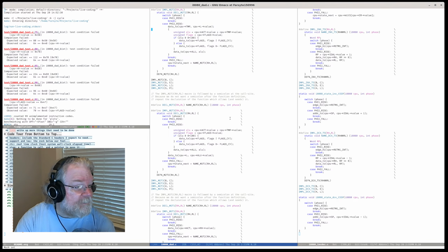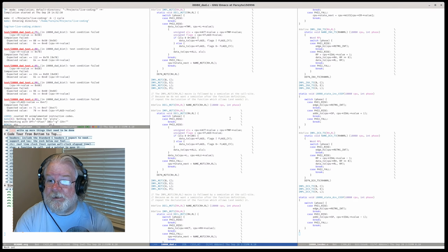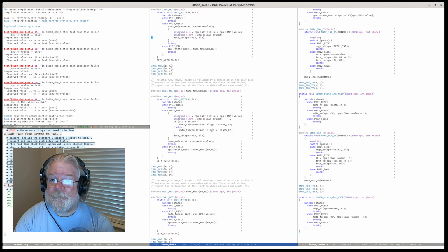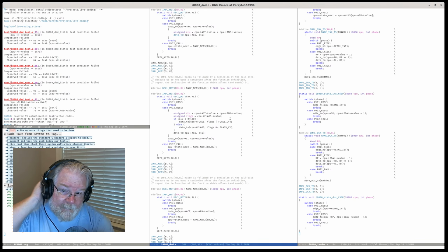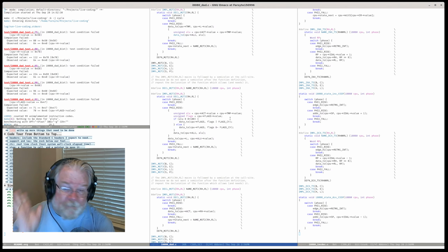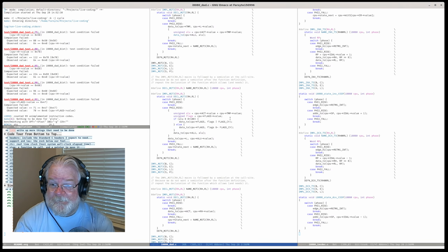So during M2T2, we want to commit the result to the ALU, but not to the carry flag. And during M2T3, we already have the result in the ALU, but we need to recompute it so that we can pick up the carry flag properly. All because we're not carrying more data than we should.